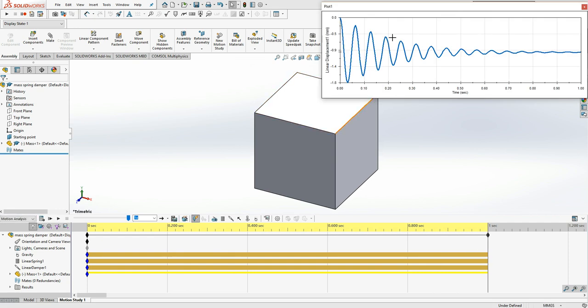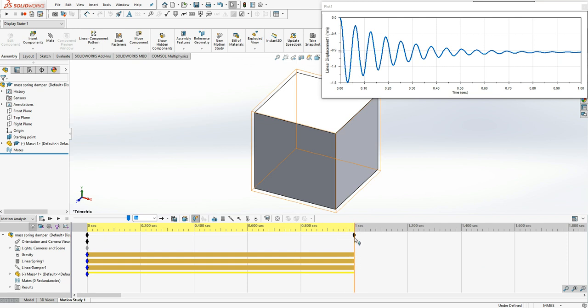Now look at that. Still remains, but you're starting to see a smoothness that's occurred within it. I don't think that that's really error. We could put more time steps on that. We could put more frames per second on that, but it's very smooth output. And even looking at that, look at this. You still have some behavior beyond 1 second. So what I'm going to do is just boost it up and go 1.4 seconds, and let's run it again.